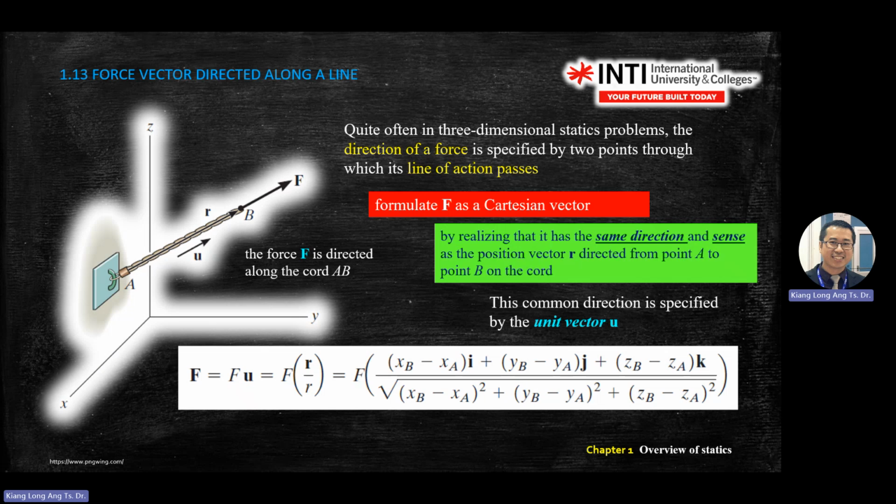Don't worry about this equation. This one was already derived just now. Okay. Important is you understand what this is. What is unit vector? Unit vector, again, is vector divided by magnitude. This one is R. Unit vector is linked with position vector. So starting from today, in your diagram, previously you only see a force. Today onwards, F is normally given in the question, and you need to add R and U in your diagram if you're seeing 3D problems.